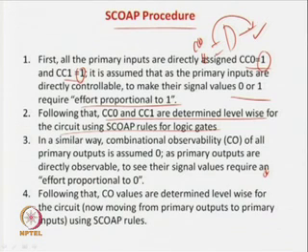If you know CC1 and CC1 of these, what is the value of CC1 of this net? That is the level propagation of how difficult it is to control and how difficult it is to observe. All those rules we will study. So, for primary inputs you apply CC0 and CC1 as 1 and 1, that is, the difficulty to control the primary inputs is 1 and 1, and that is fine.